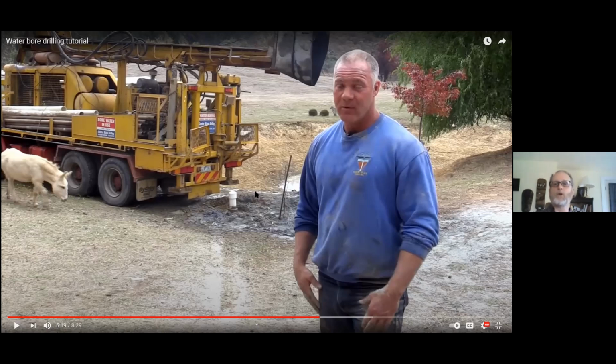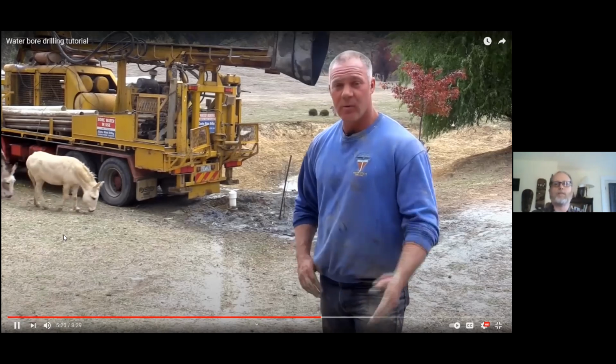So he's talking about using a more rigid type of casing, because if you can imagine the bore that has just happened, material can collapse and then put pressure against the casing. So he wanted to choose a material on the casing that is going to support and stand against any of the pressures that come from basically 18 meters below grade. And then what he'll do is put in a supporting grout between the existing ground and the casing. And then the pump will go down the middle of the casing to pull water out. Do it properly the first time, or just don't do it.